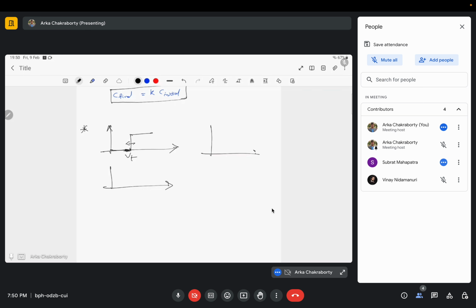So what happens basically? We get something like this, and subthreshold swing is defined as the slope by which my current is reducing. Okay, got it? This is my subthreshold swing, and I think subthreshold swing is 1 by d(log ID)/d(VGS), if I remember correctly. It is basically saying how quickly my current is reducing when I reduce the VGS, how quickly it is going towards zero. And generally a high subthreshold swing is desired, that is, as I reduce the VGS, my ID should immediately drop. Okay, this is the definition of subthreshold swing.